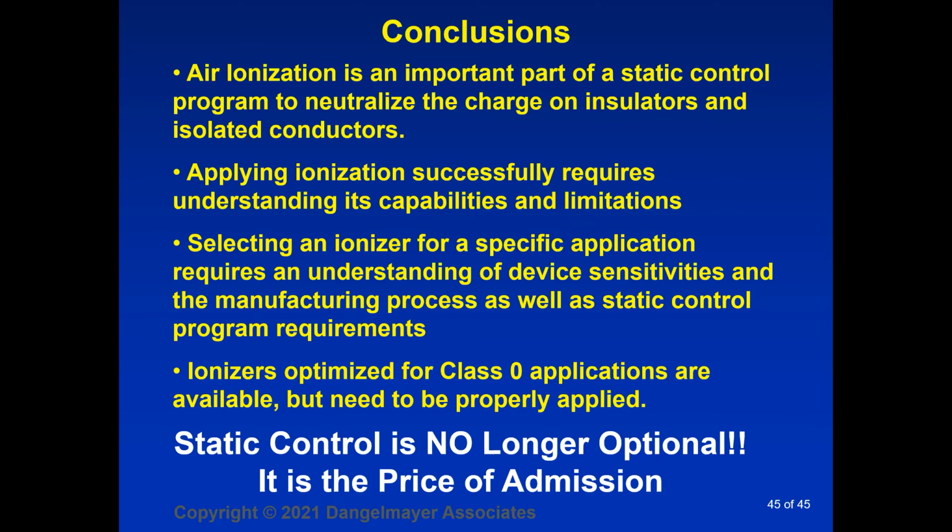You have to make sure that it works fast enough with your product flow. And you have to make sure that it meets your static control program requirements. Is the discharge time compatible? Does it do what you want? Is it balanced at the level that's appropriate for the sensitivity of your devices? These are things you need to know in order to choose that ionizer.